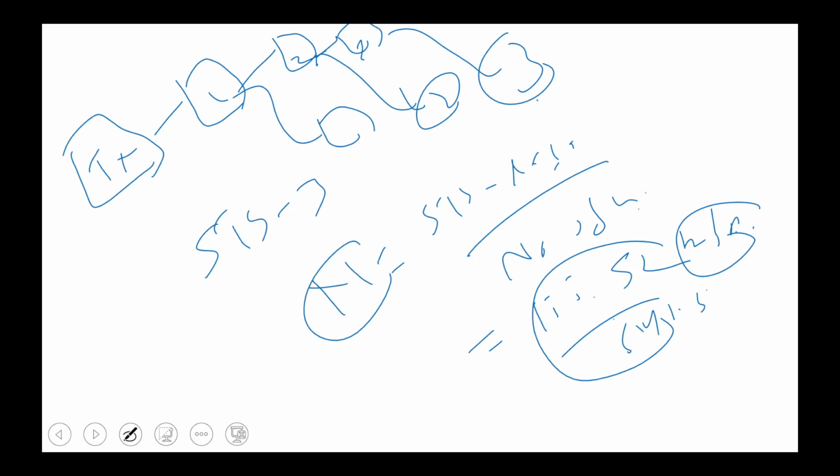The video signal is distributed to the subscribers. Each receiver needs a minimum of 100 nanowatt to operate satisfactorily. Optical taps couple 5% of power to each subscriber. Assume 0.5 dB insertion loss for each tap coupler and a 1 milliwatt transmitter power. Find the number of subscribers that could be added to the bus.